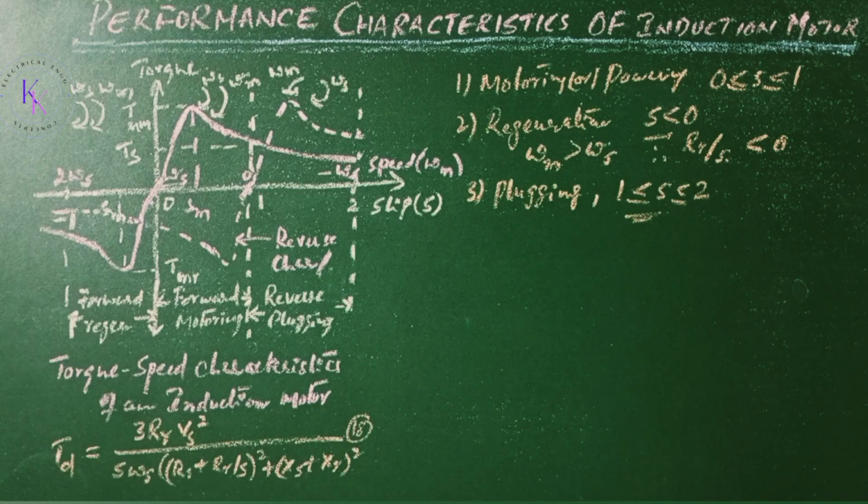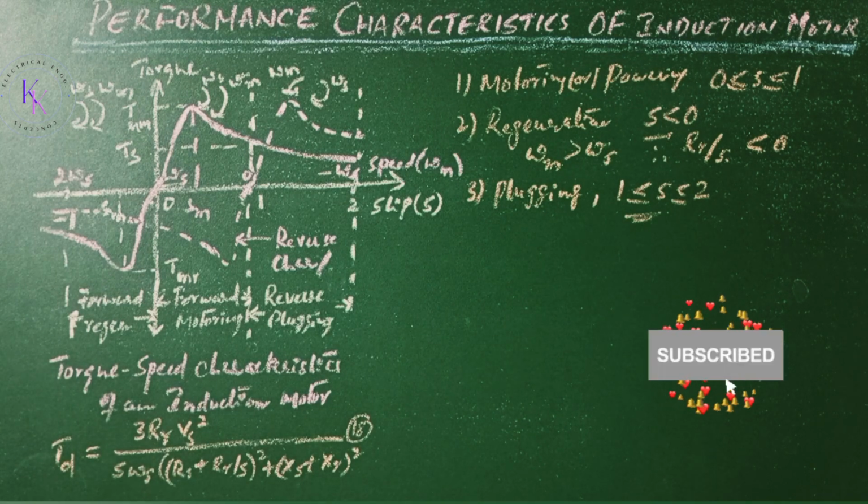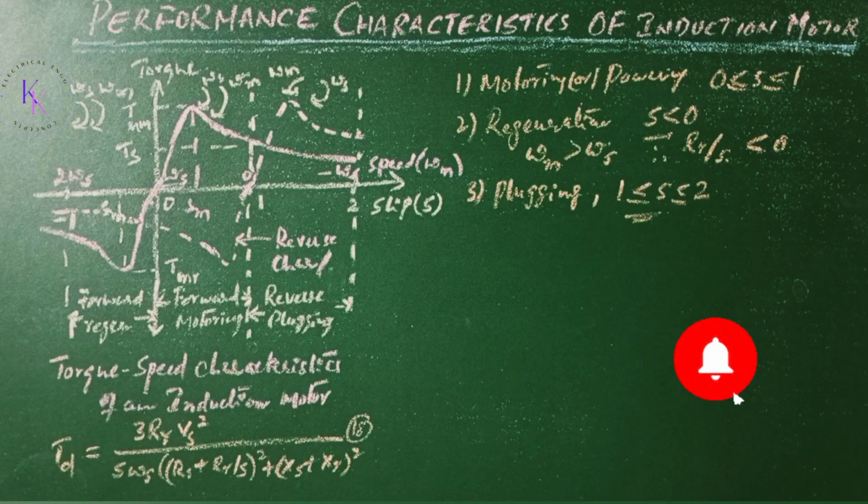The developed torque, which is in the same direction as the field, opposes the motion and acts as a braking torque. Since S is greater than 1, the motor currents will be high, but the developed torque will be low. The energy due to the plugging brake must be dissipated within the motor, and this may cause excessive heating of the motor. This type of braking is not normally recommended.